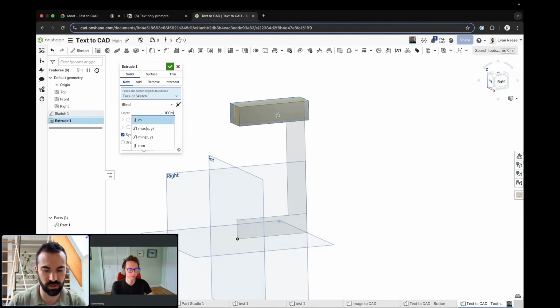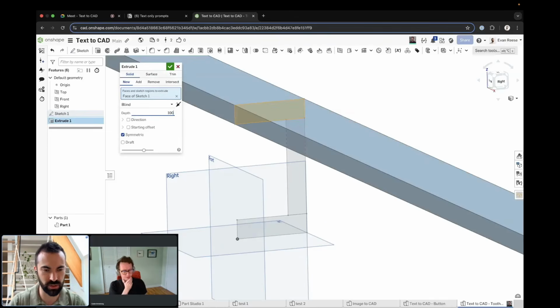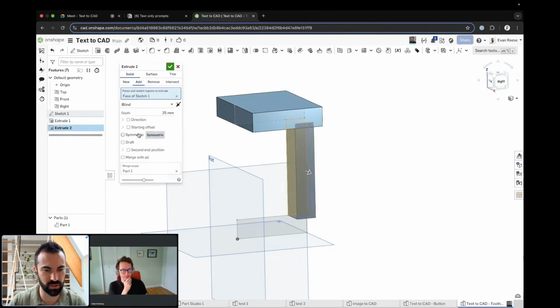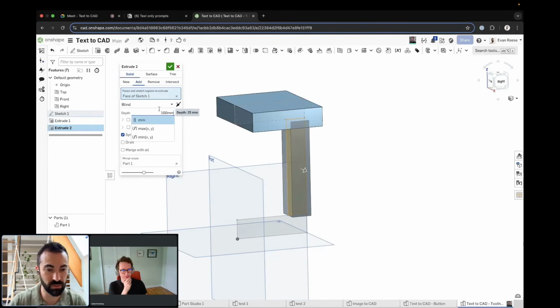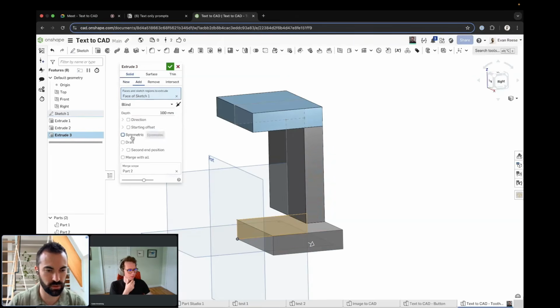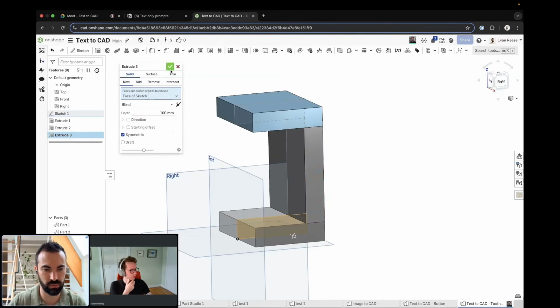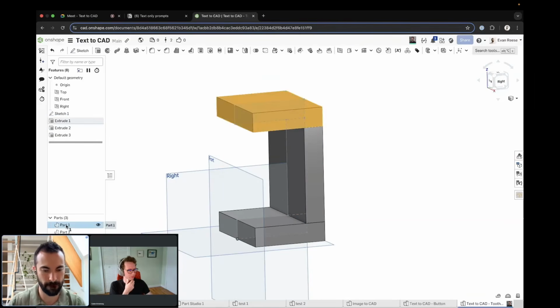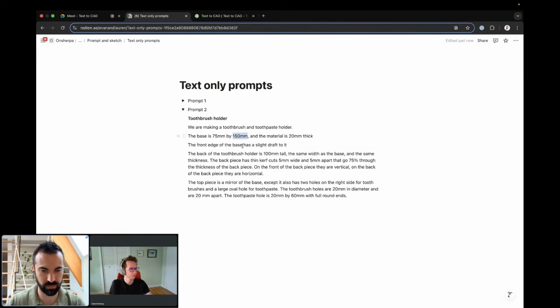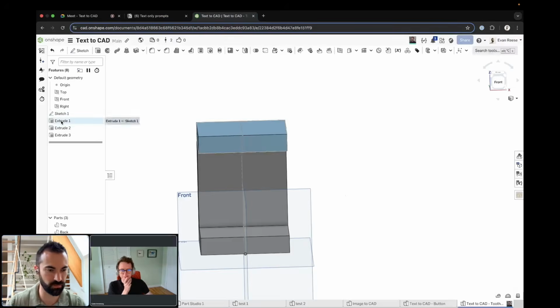And 100 millimeters, not 100 meters. That might be too big for your bathroom. Oh my god, I did it again. Okay, shift enter to make another one. Symmetric, 100 millimeters, and new. Okay, so I have this. I'm going to name that top. Shift N is what I'm using here as a hotkey to rename those. Okay. All right. Something's feeling off. Okay. Got it.